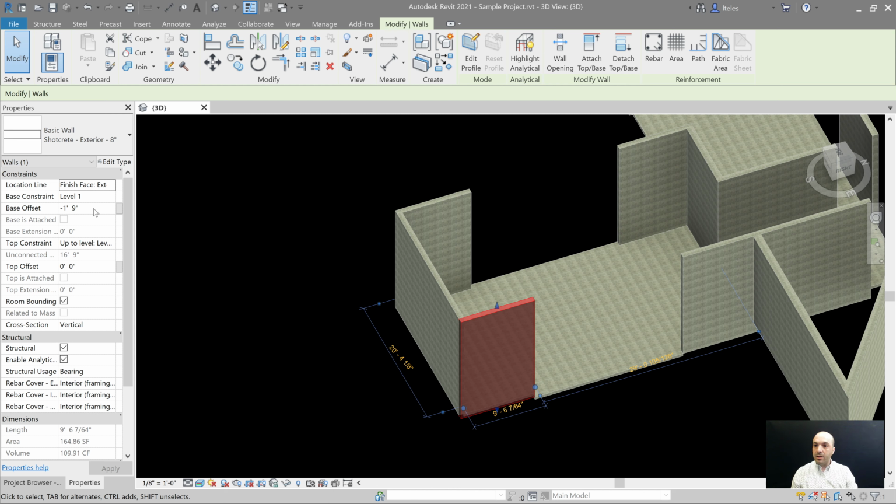However, once you start getting into crazier numbers and more complicated structures, you can use this cool little trick. Change this value to a formula by hitting equals in front of it. Okay? And then at the end of it, say -1 foot. Okay? And now hit OK. And you can see that Revit did the math for you.